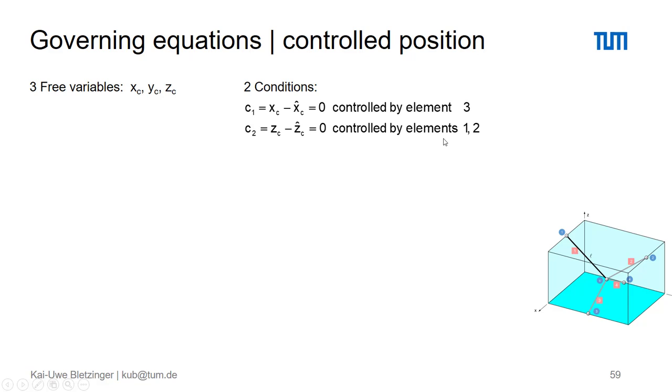That means it's exactly one of these cases where we start with introduced force densities of elements 1 and 2 and simultaneously scale them through the procedure. That means the relative relation between these force densities will remain.